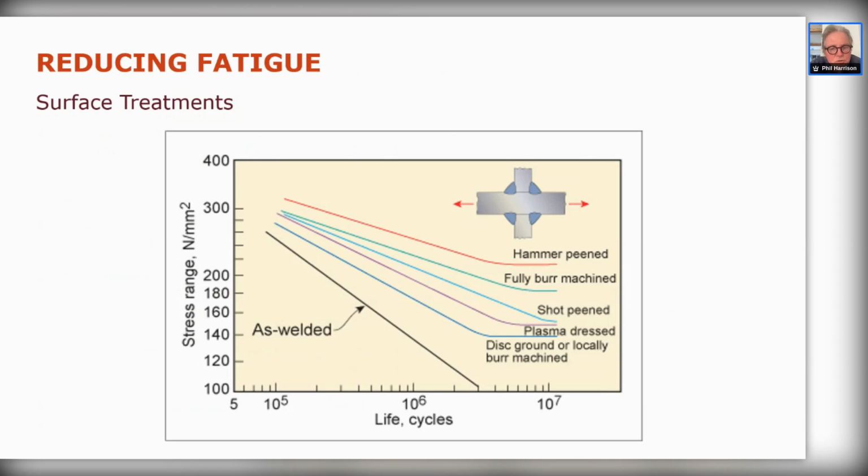The majority of structural components in commercial airliners, on metallic ones obviously, are shot peened. It is not the ultimate method for putting very, very deep compressive stresses in, but it means you can cover large areas very, very quickly. So again, putting compressive stresses in can alter the fatigue life of a component and give it orders of magnitude longer life than it would have otherwise.